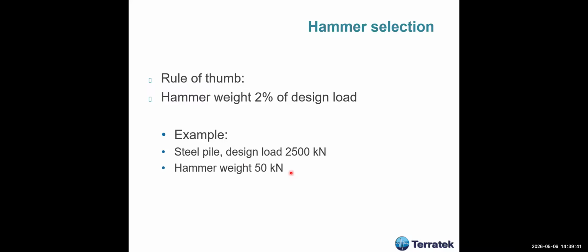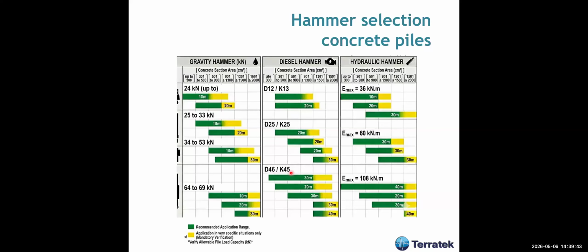The other thing, which I do a lot, is to talk to the manufacturer or to talk to the contractor. Usually I use their experience in order to select a hammer. There are different kinds of hammers, for example gravity, diesel, hydraulic, for particular loads.